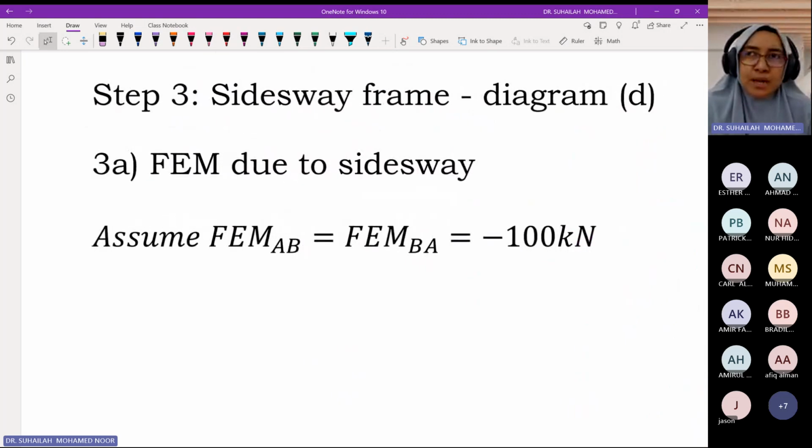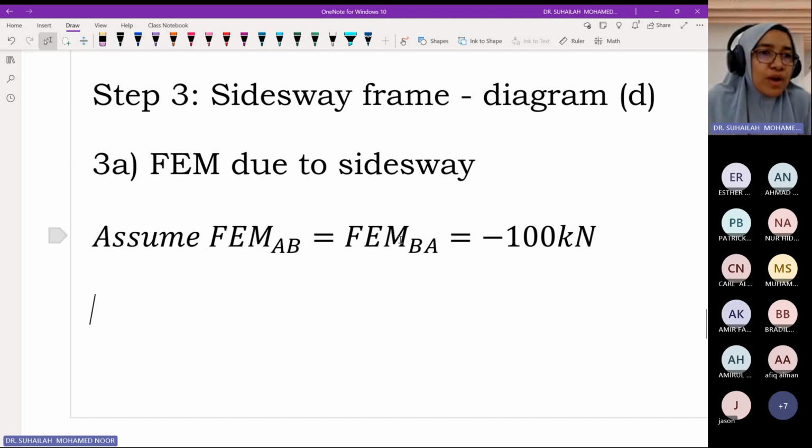I made the video on Tuesday where I also showed the method in the book that explains the substitution. And on the landing page of the website I shared with you, in the example I showed the table. I actually simplified this step. This part is actually a ratio, so I simplified the steps in the table calculation. The formula for FEM: we use 6EI delta over L squared. That is the standard formula for FEM.